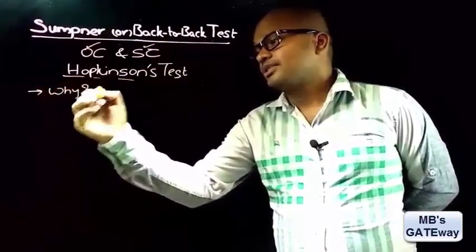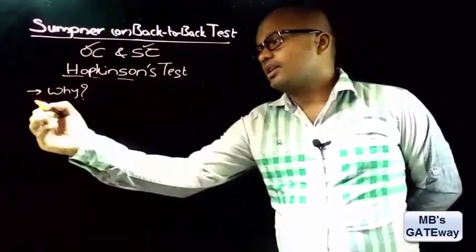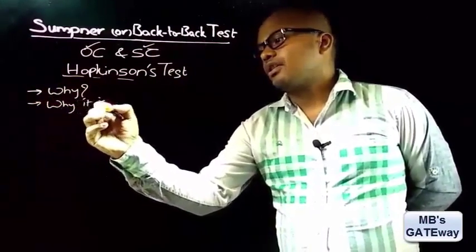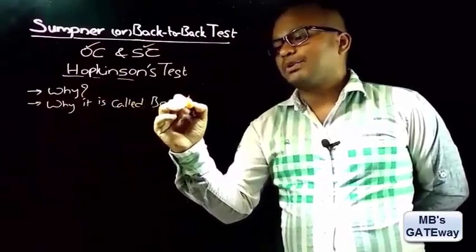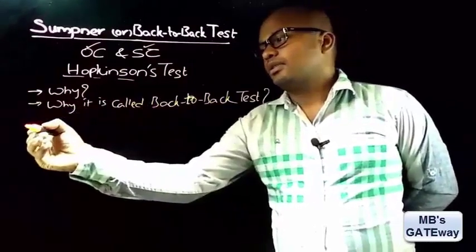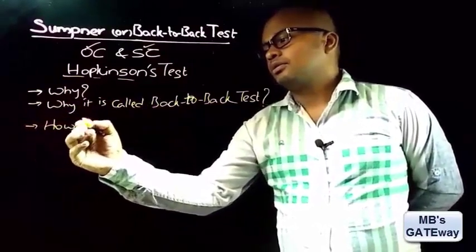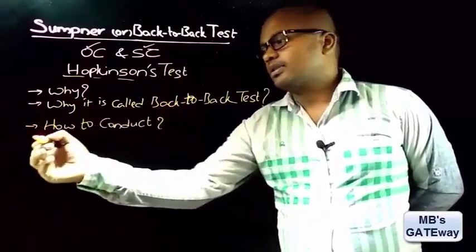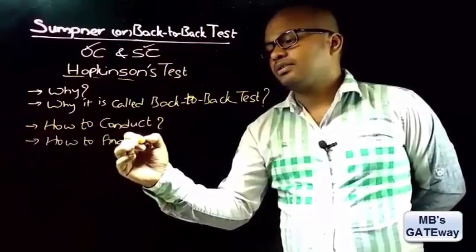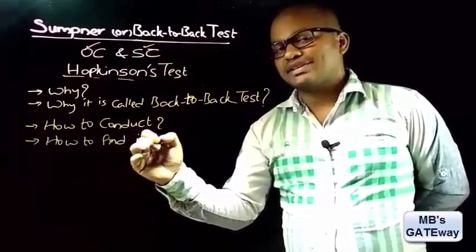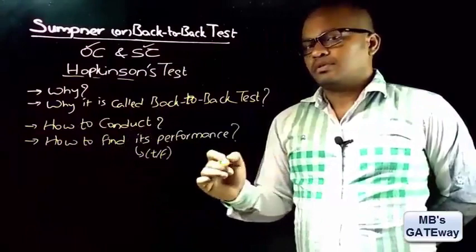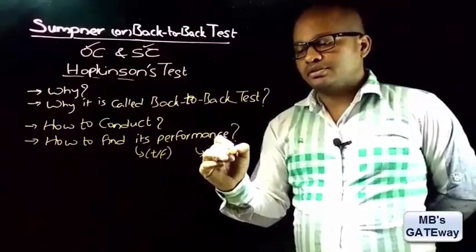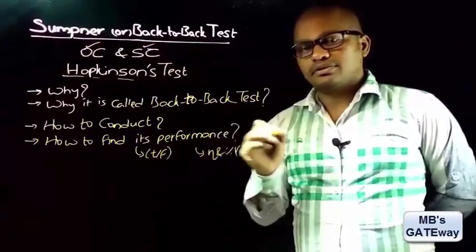why Sumpner's test is to be used, why it is called back-to-back test, how to conduct this Sumpner's test, and how to find the transformer performance, that is, how to find the transformer efficiency and percentage regulation.